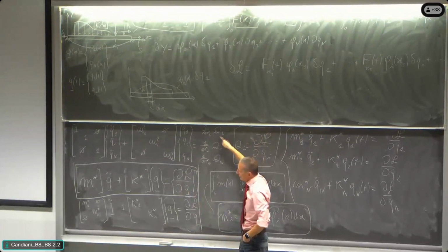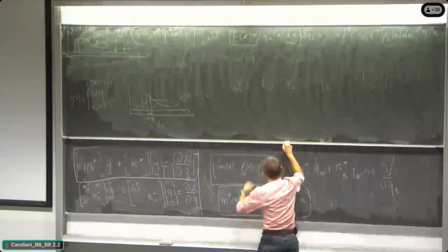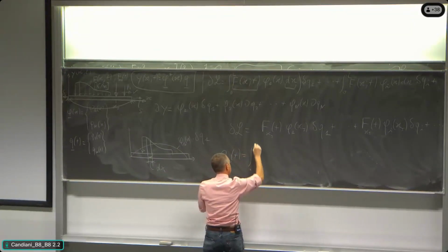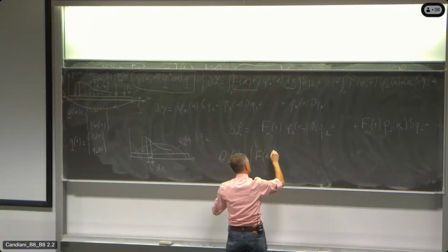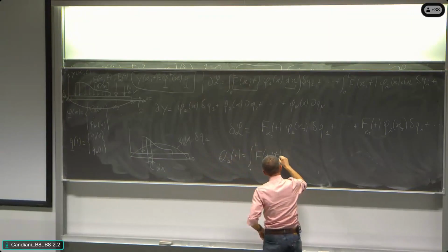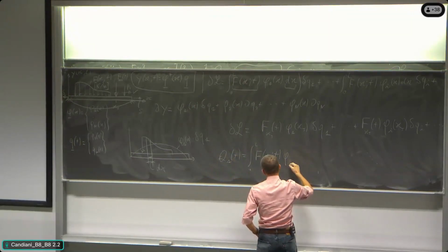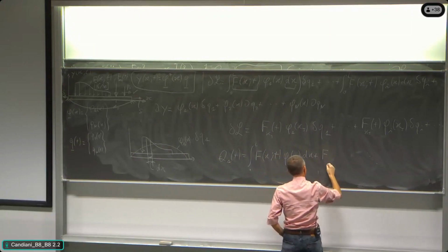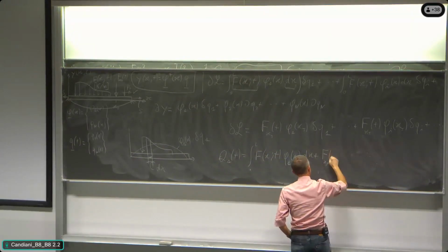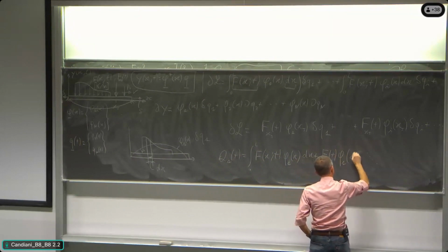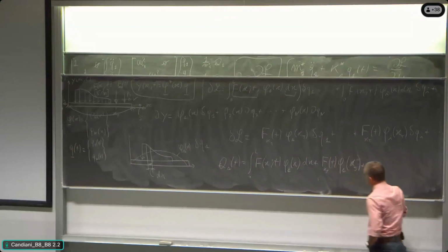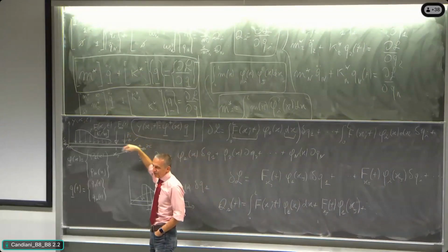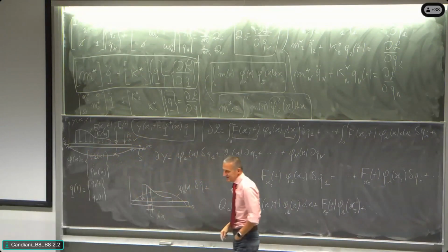And so if I want to write what I am expecting, for the first equation, this q1, the quantity q1 function of time will be the integral from 0 to L of the distribution of force, in space and time, times phi 1 function of x dx, plus f at the location xj function of time times phi 1 at the location xj, plus, and let's not forget this, the load moving, that is the car, the truck that is running over the bridge.